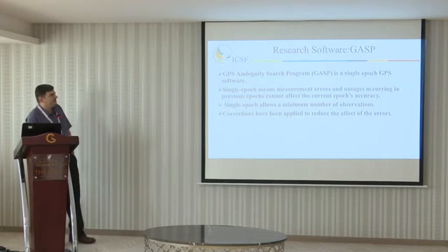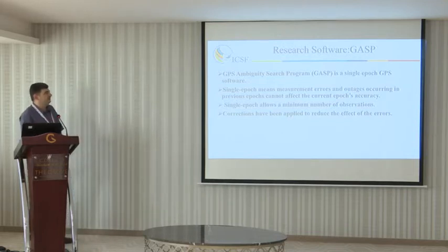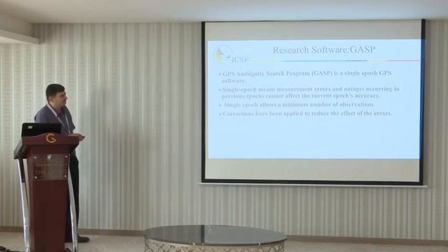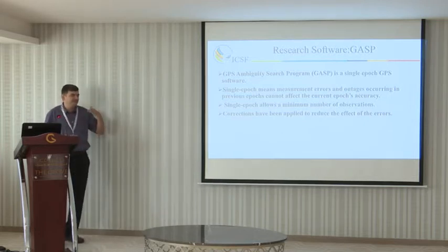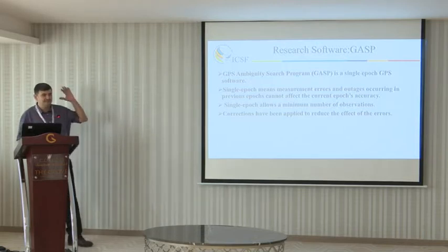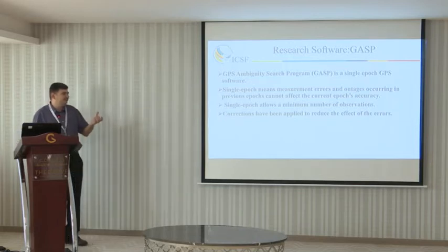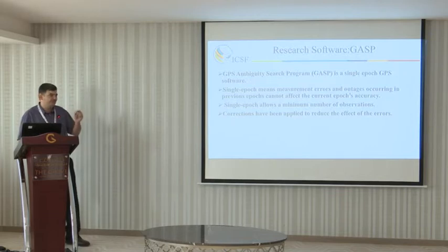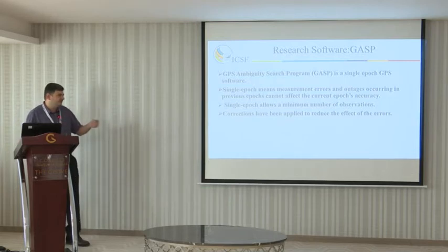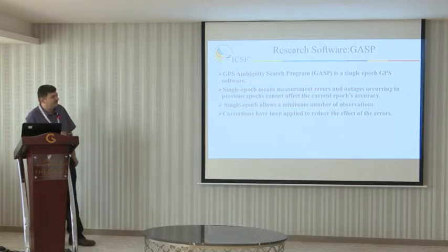Now, for my research, I used software introduced by Newcastle University. It's a single epoch GPS software. Let me point out the meaning of epoch here. I said satellites provide data over time. Any second, any minute, there's data coming from the GPS satellites. But the receiver on the ground is set to collect the data every second, or 30 seconds, or minutes; there is a setting for the receiver. It can't receive continuously. We call it an epoch. It's just one package of data coming from the GPS satellite. So each package, we call an epoch.